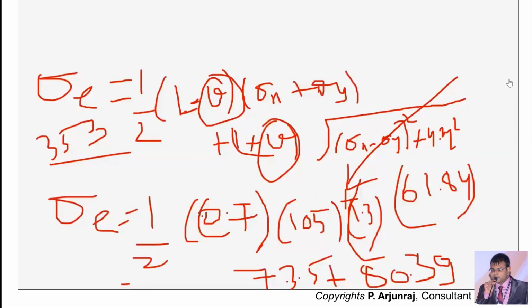Where you have rubber, it will have a different value. Rubber is a part of soft material, for which the bulk modulus is going to be higher than the shear modulus, and you can take the Poisson ratio nearing 0.5 for a soft material.